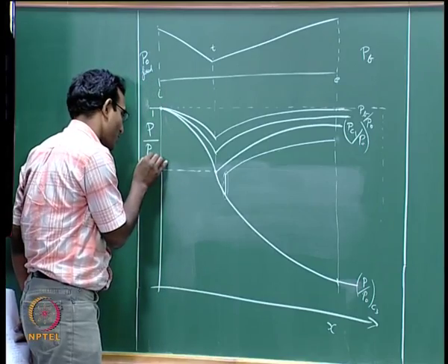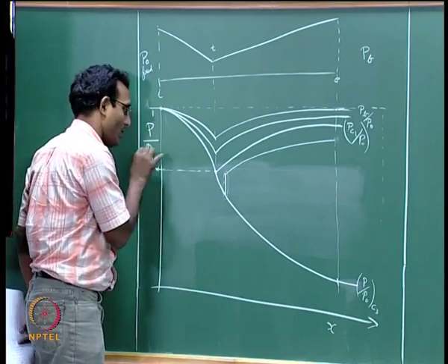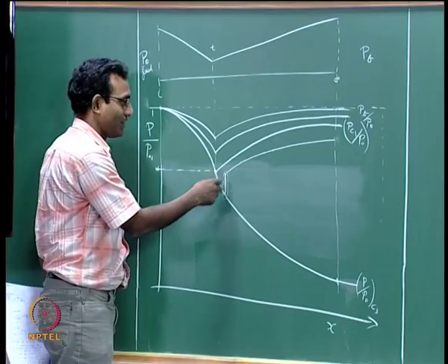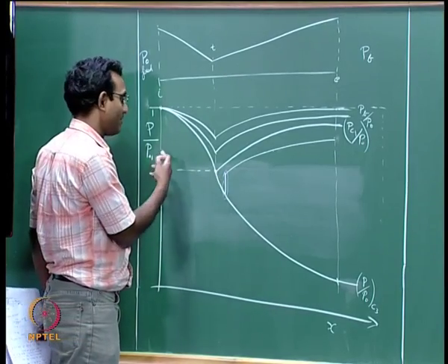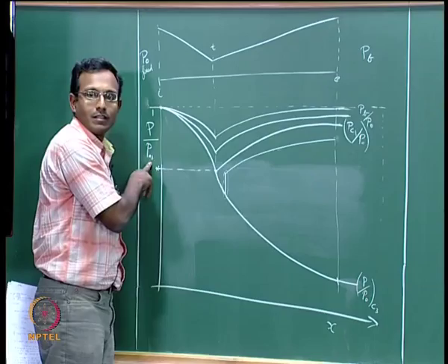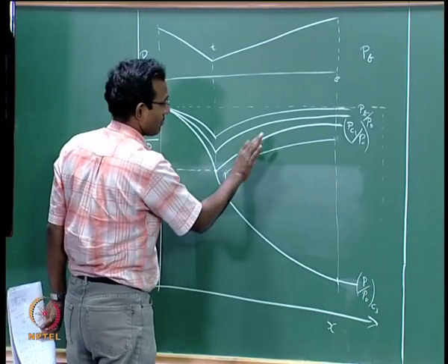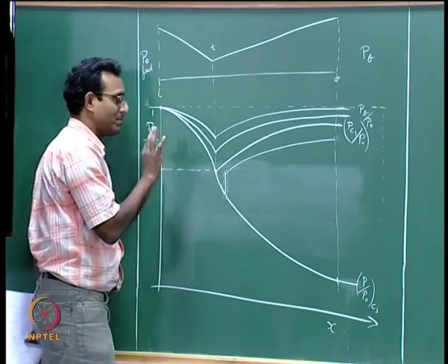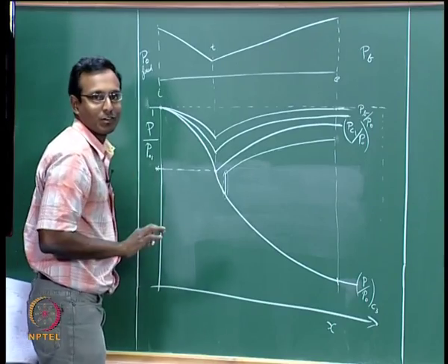That is where we have to be more careful and say P divided by P01, so that in case of the shock existing, we have to be very clear which P0 we are using. If I use P02 here, that curve will be slightly different. We just want to keep a single normalizing factor, that is P01 for us.